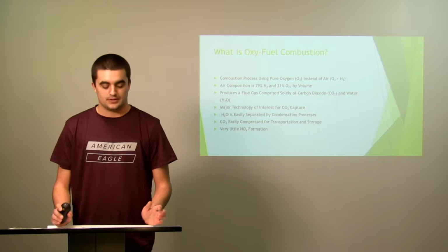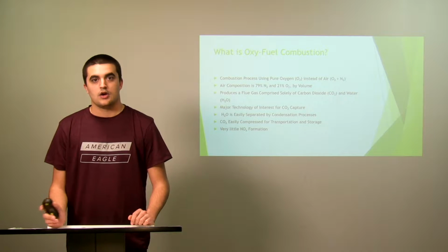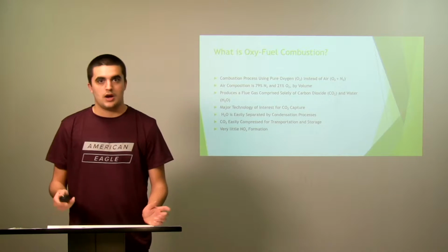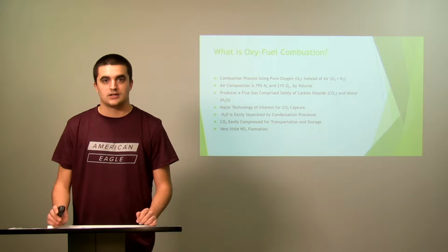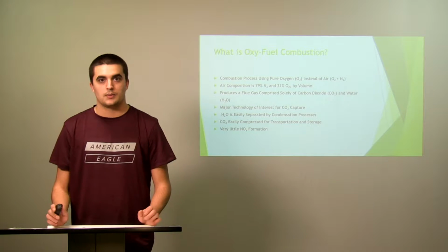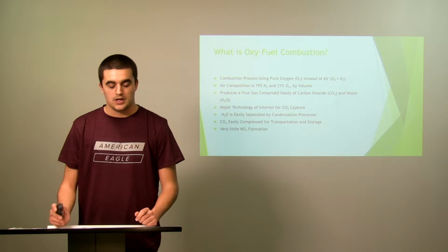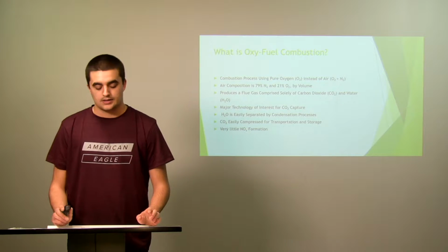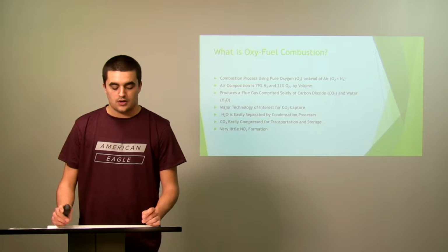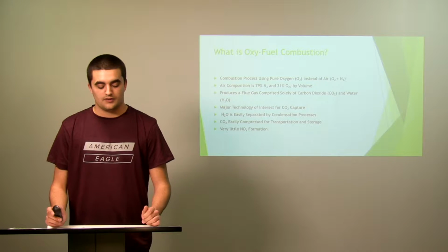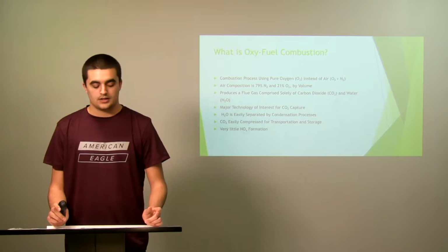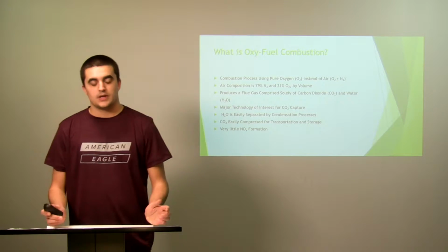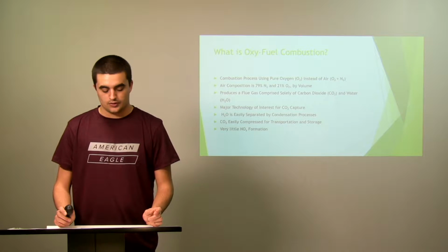Well, it's actually a simplistic process that uses oxygen for combustion instead of conventional air. As you may know, air composition is typically made up of around 79% nitrogen and about 21% oxygen by volume. Without using that, we can use a lot less volume of gases for the combustion process. Also, using oxygen instead of air produces a flue gas comprised solely of carbon dioxide and water. This is why it's becoming a major technology of interest for CO2 capture.